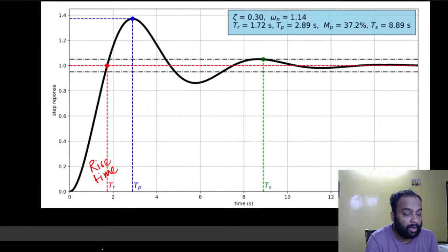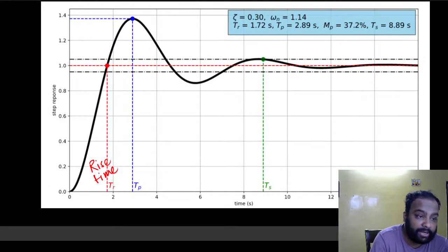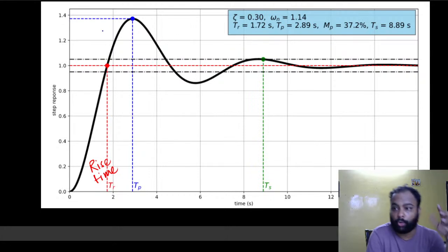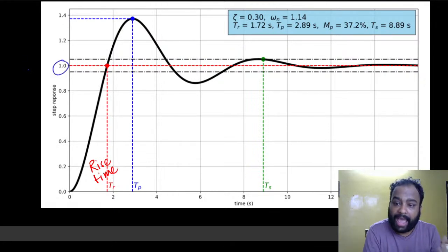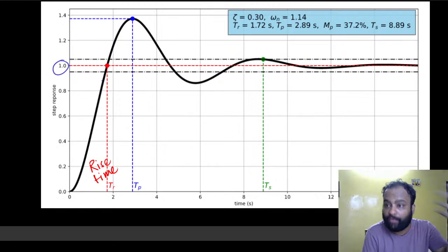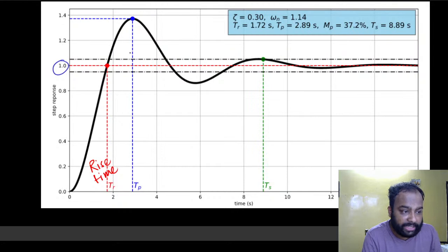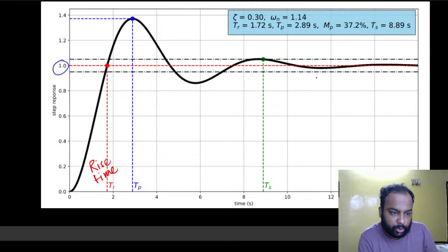All right. Then it again rises up beyond that, and it reaches a peak. So basically what happens, this one is the final value of the output, right? And before it can settle at the final value, it can peak up. It will automatically overshoot the output. So the output is overshooting the final value of the response, then undershooting, then again overshooting, undershooting. So oscillation, but the oscillation will automatically die down, right?